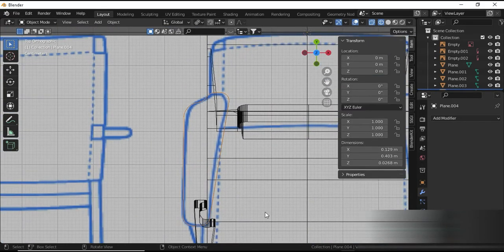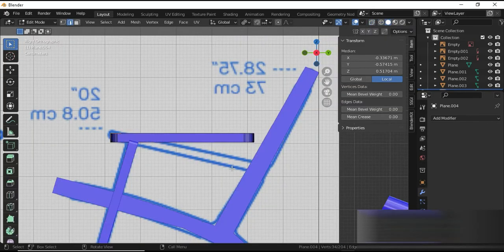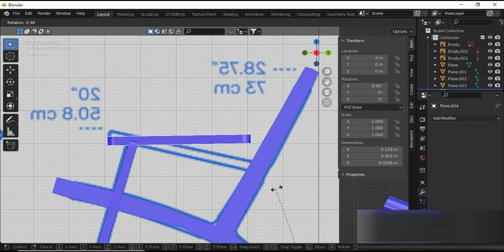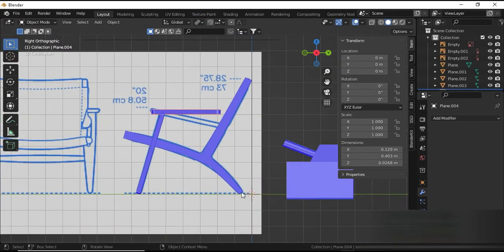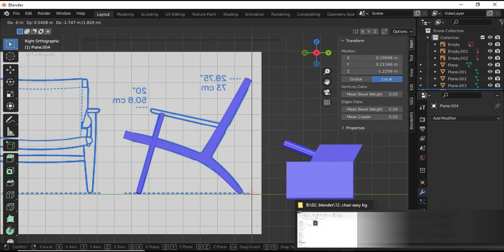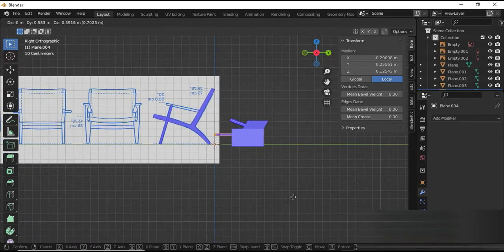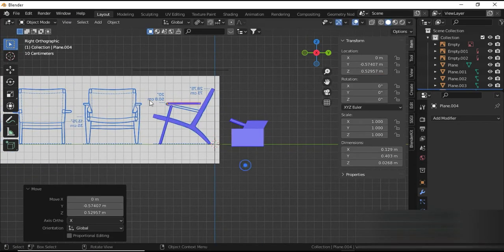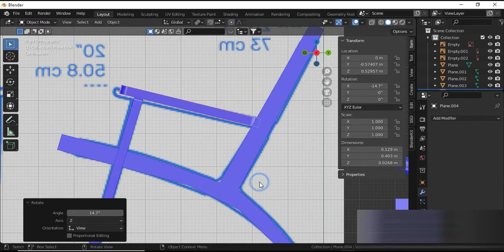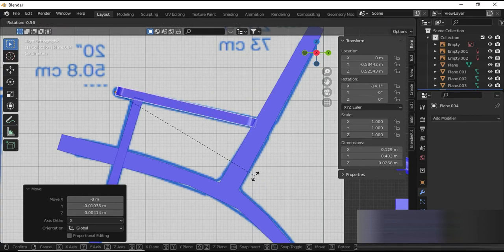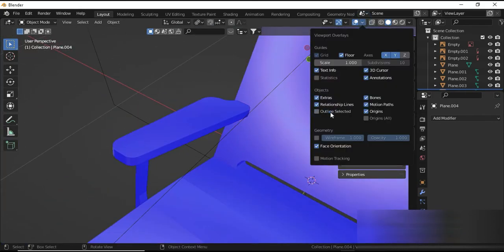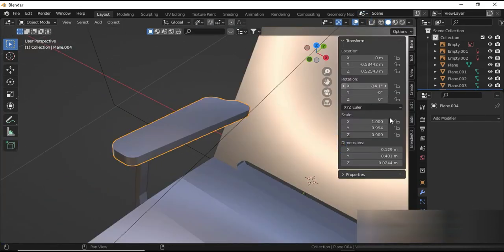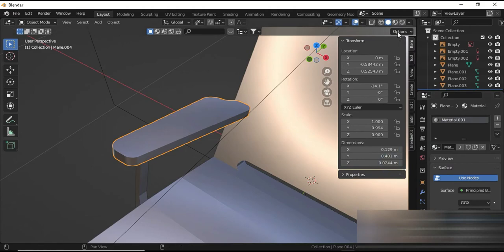So guys, our supports are done, and I think we have modeled it quite well. But make sure you extrude it on the blue side, I mean, just make sure your normals are correct. So now we rotate. Make sure that during modeling, you're constrained to a particular view, for example the front or the left or the side. That's how modeling becomes easier.